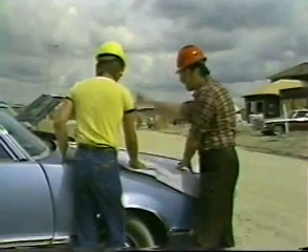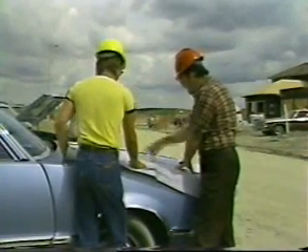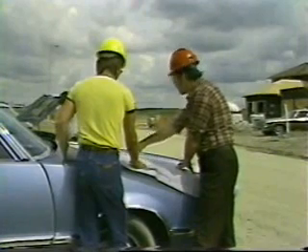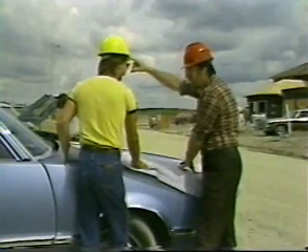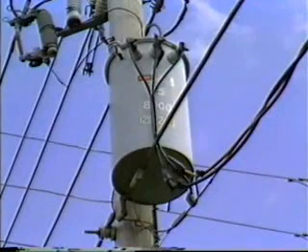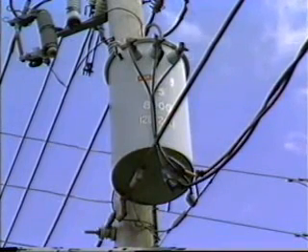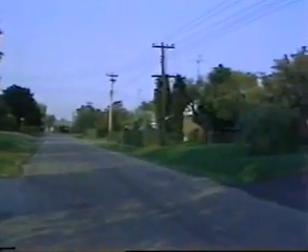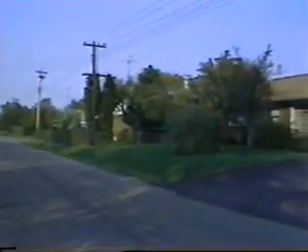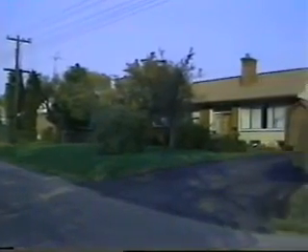The actual value of coincidence factor will be set by the utility company based on experience with different types of loads in different locations. The utility company must be prepared for the load to grow and will normally take account of this probability in their installation. For example, in a new residential subdivision, a small 25 kVA single-phase transformer may initially be sufficient. Then, as the subdivision grows, a larger transformer can be installed or additional transformers added.